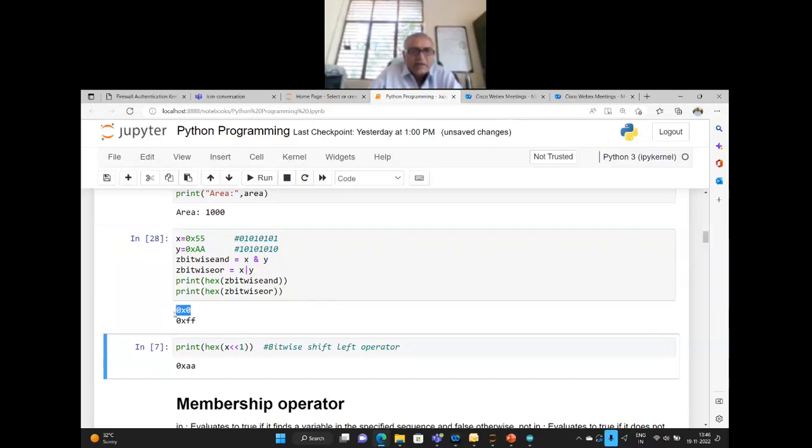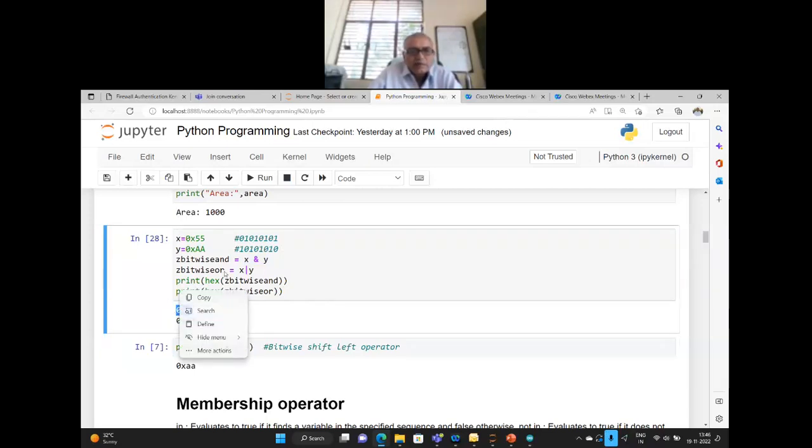Now we are doing an ORing operation. ORing operation means if any of the inputs is 1, then output will be 1. Or if both of the inputs are 1, then also output is 1. Output will be 0 only if both the inputs are 0. So here you can see there is at least a 1 everywhere. So 1 0 will result in 1, 0 1 will result in 1, and so on. So the result will be all ones. All ones is FF in hexadecimal value, right? So you can perform bitwise and, or and all other logical operations by giving the instructions.